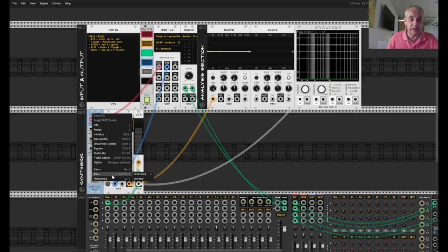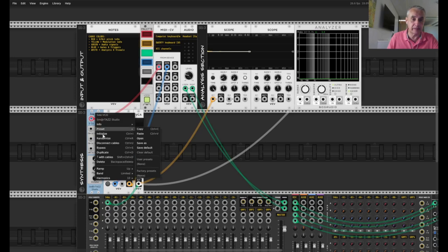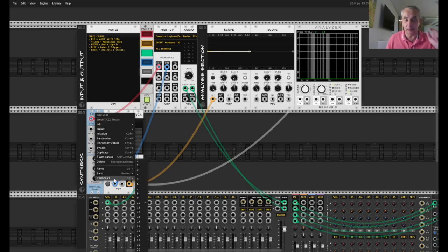There we have the band unlimited, which is the default, which basically is the mathematically correct sawtooth, but which has aliasing issues. But you can also go to band limited. And at the moment you select band limited, it means that you can set the number of sine wave harmonics that are used to generate the sawtooth. If you look at the formula for a sawtooth, it's a formula where you have the basic sine wave, then double the frequency, 3 times the frequency, 4 times the frequency in ratios that are added on top of each other to generate a sawtooth wave.